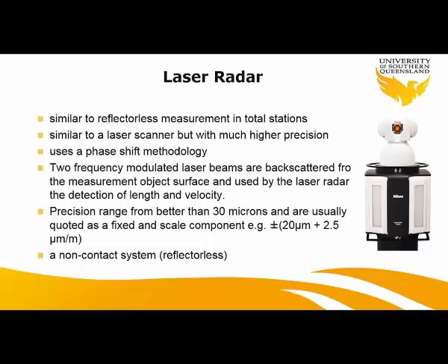The next system I'm going to talk about is laser radar. It's pretty much like reflectorless total station, so the principle is the same. It's also similar to laser scanning, so it sends a laser beam but with much higher precision. That's why we are using laser radar, not laser scanning, because it has a more precise accuracy. And then you use the phase shift techniques to measure the distances. So it has two frequency modulated laser beams, and it sends them to the object. There is no target required for this, so it's a non-contact system.